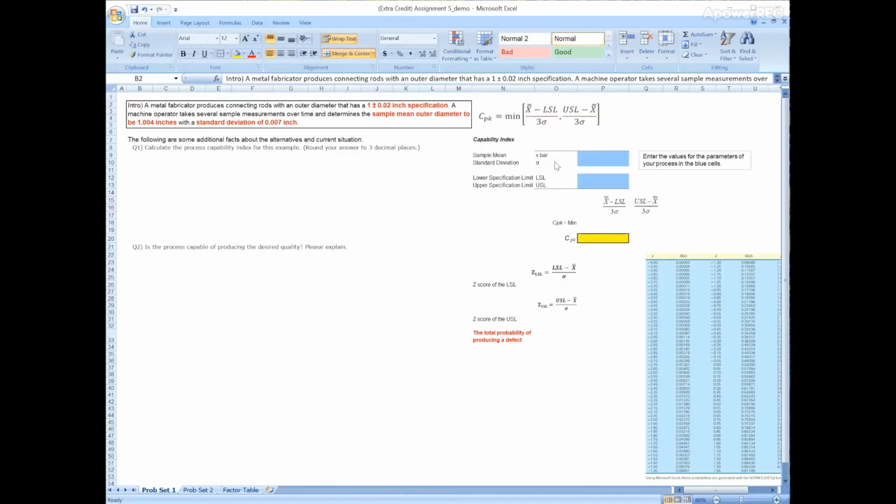The capability index is used to measure how well a process performs in terms of design specifications. If the specification limit is larger than the 3 sigma allowed by the process, then the mean of the process can be allowed to drift before readjustment. The capability index CPK is calculated by dividing the range of values allowed in the design specification by the range of the values produced during the process.